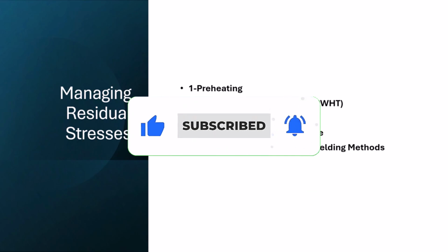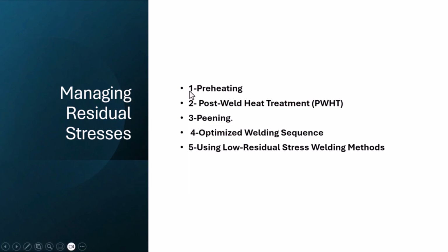While we're dealing with material which is at 20 degrees centigrade, imagine that we do the welding after preheating and it is already at 100 degrees centigrade. This slows down the cooling rate, which is pretty useful and is one of the most widely used processes for managing residual stresses.